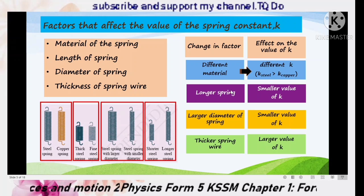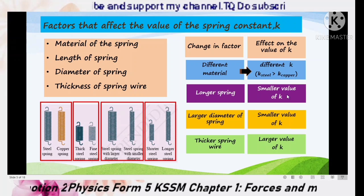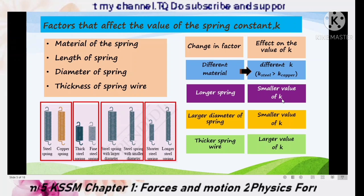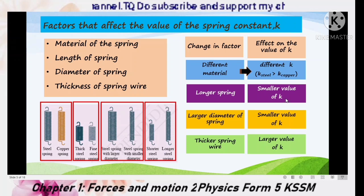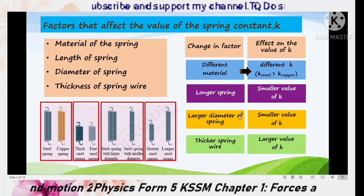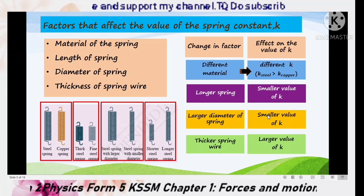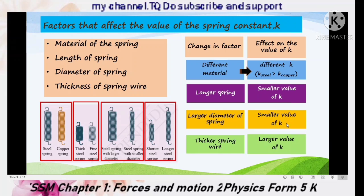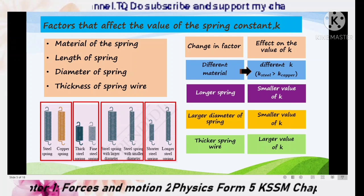Length of spring. When we use a longer spring, it produces a smaller value of k, meaning it becomes less stiff. When we use a larger diameter of spring, it also produces a smaller value of k, or is also less stiff.